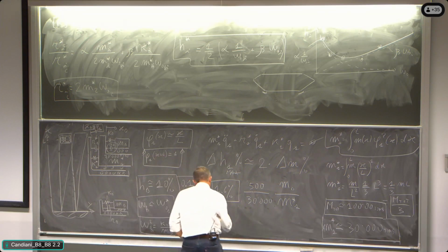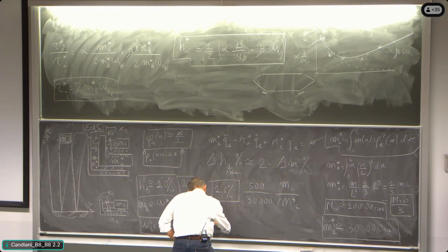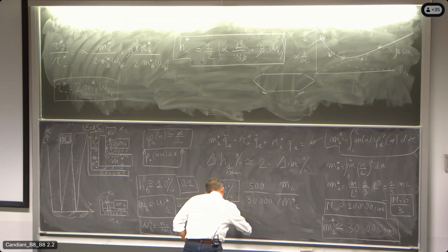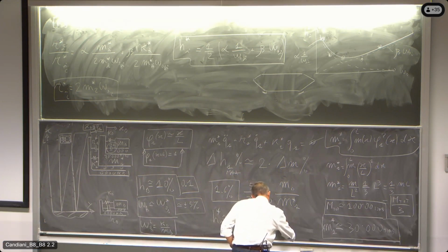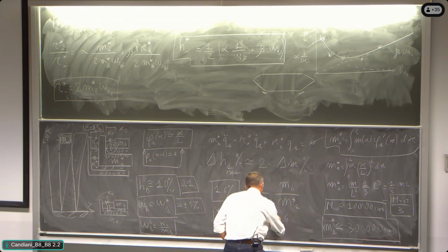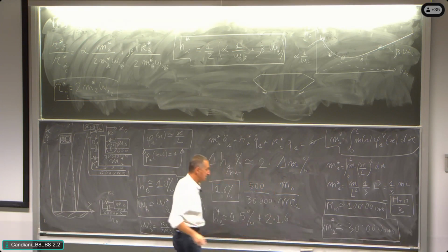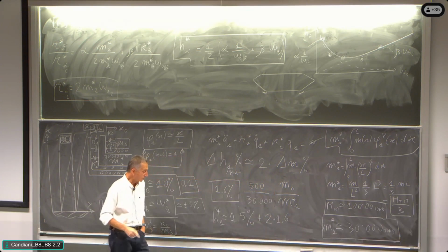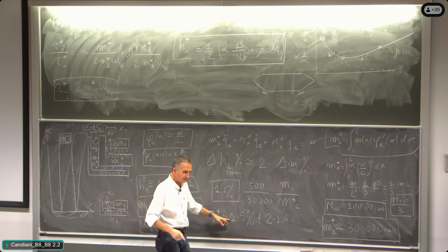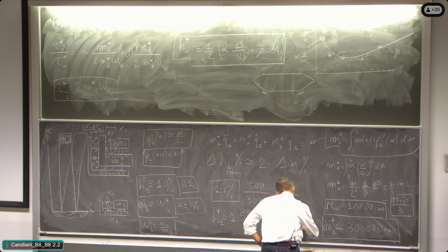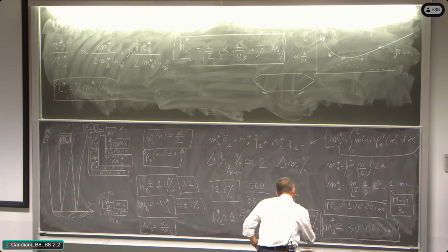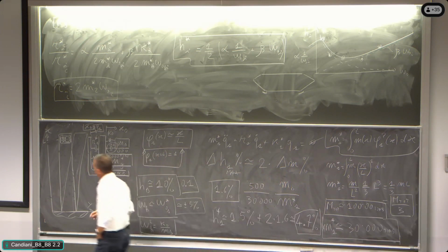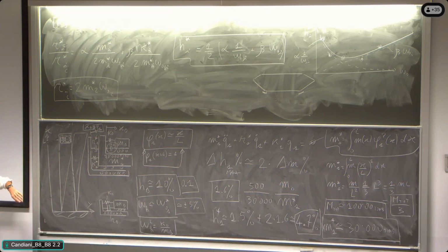The intrinsic damping of the building is about 1.5% plus 2 times 1.6, makes 1.6, twice is 3.2. 3.2 plus 1.5 means 4.7. About 4.7%.